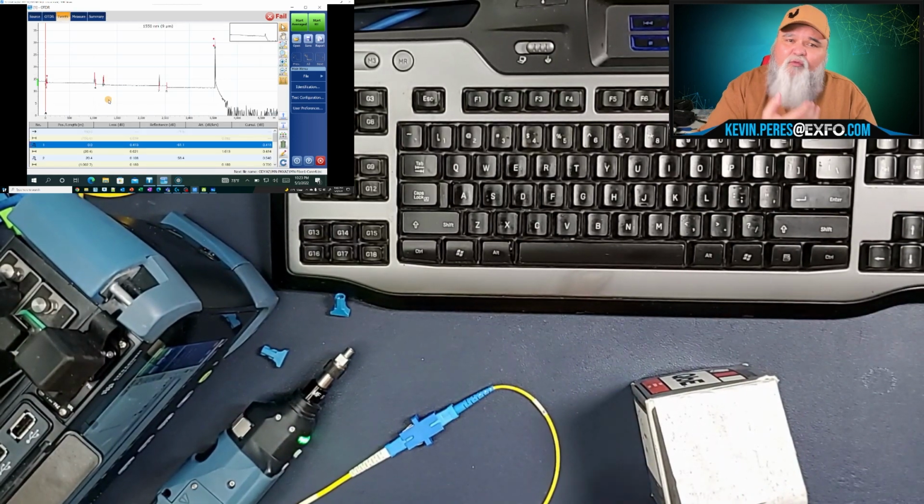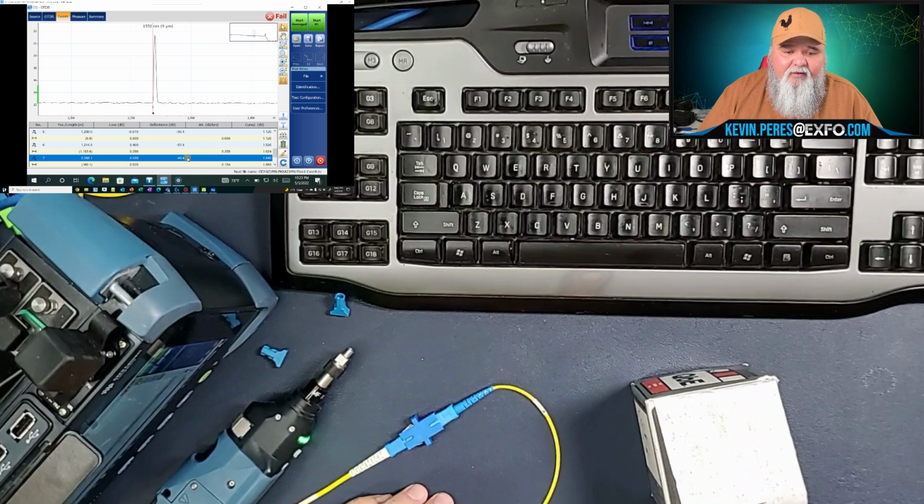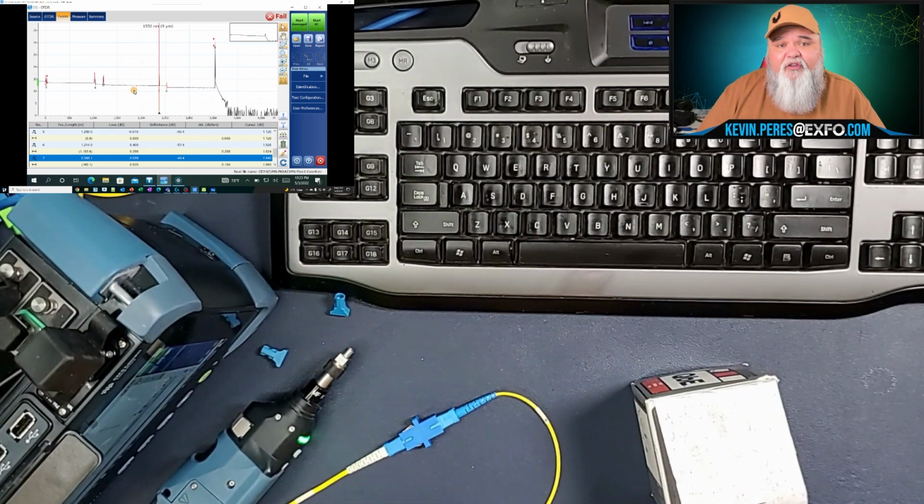So if you're using systems with Raman amplification, with any sort of amplification at all, these front-end connectors are critically important to troubleshoot, right? So right now, the highest reflection connector we have is the one way out here, and it's really not even that bad. It's really good, actually. It is possible to do this in real time as well.